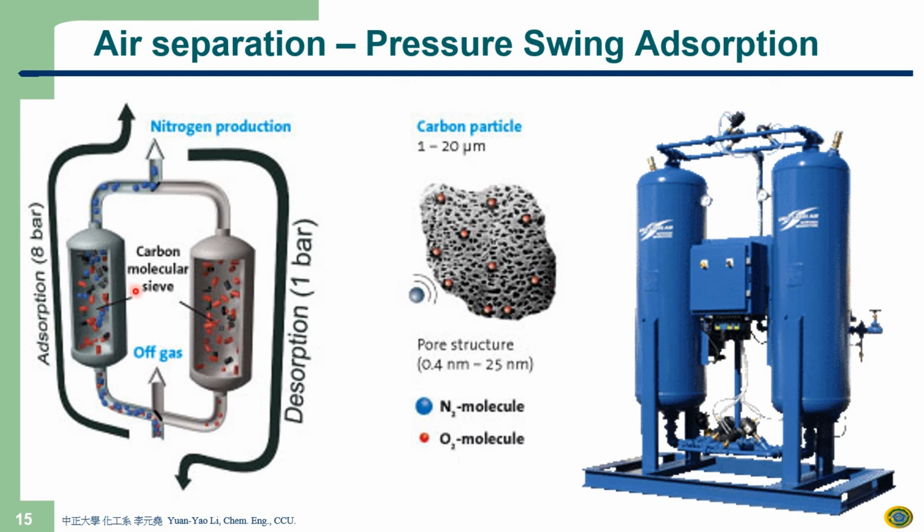So you have two tanks. One tank is to increase the pressure. So as you can see, if we have a good absorbent in this tank, and if we increase the pressure, as you can see here, the nitrogen will be released. The small oxygen will be trapped in the absorbent. Okay, so you got high purity of nitrogen released here.